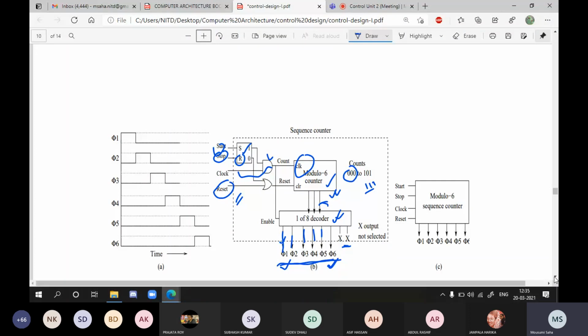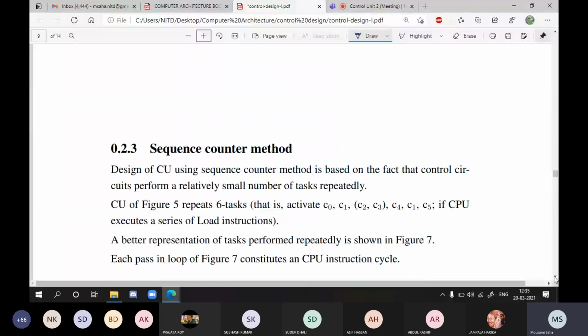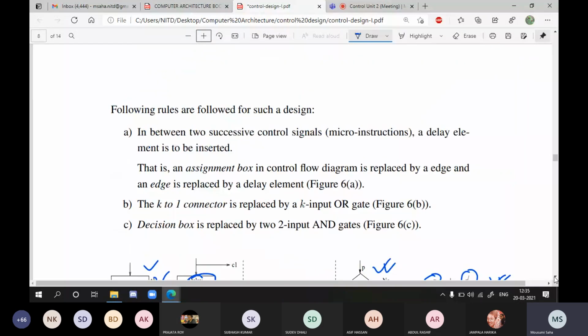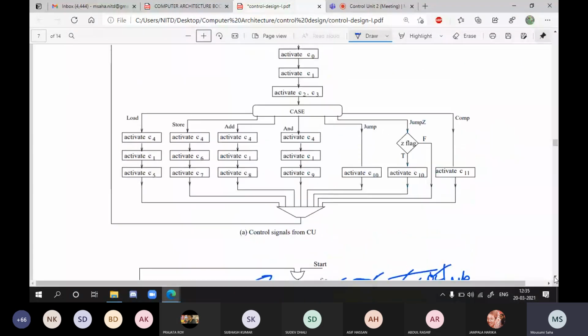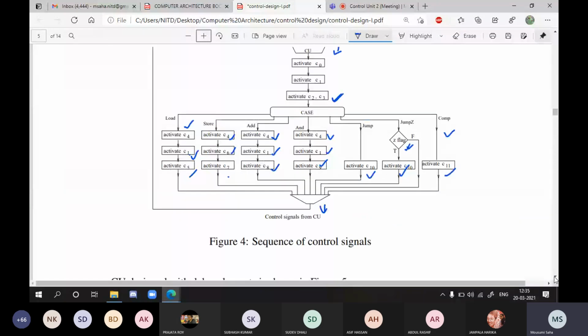So in this way we can design, and depending on your number of phases, if you need 8 phases, you have to use this signal also, when it is required, if you consider more instructions. I have considered 7 instructions, so all these are not complicated; in a very simple way I have tried to write all the steps. You can write in a different way. It depends on you how to write all the micro operations. Based on that, you have to generate all the control signals.